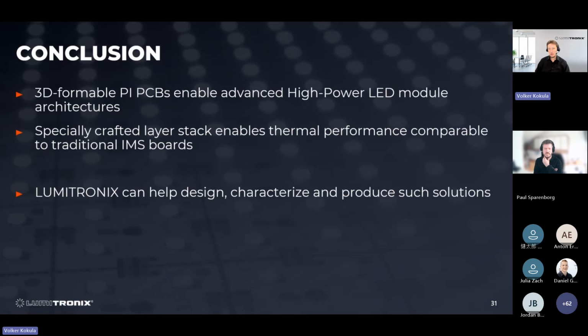We have also performed cases where we used thermal conductivity foil together with screwing, and the benefits are not as good as you might imagine, since the device under test was very small. We will have a bigger difference between screwing without TIM and screwing with TIM if the LED module is larger and you don't have this kind of good contact and pressure evenness.